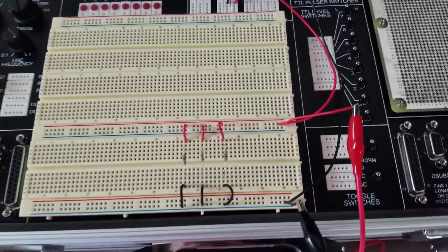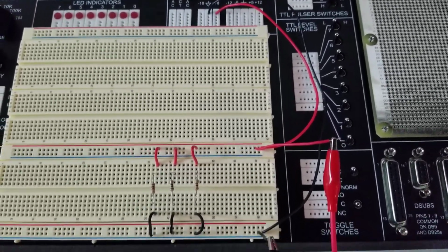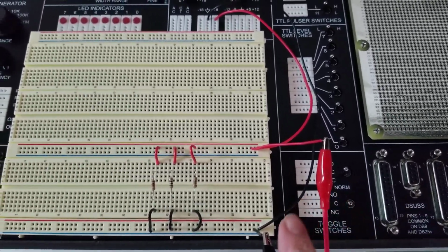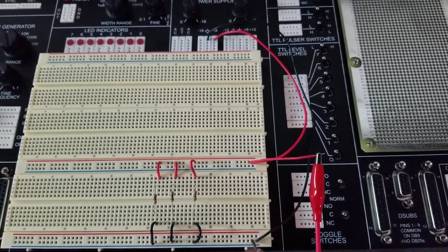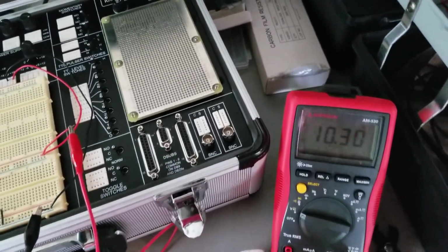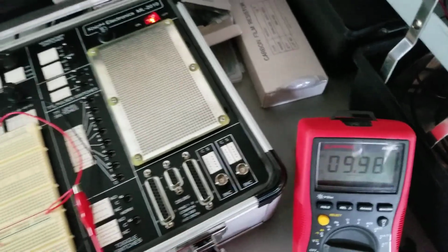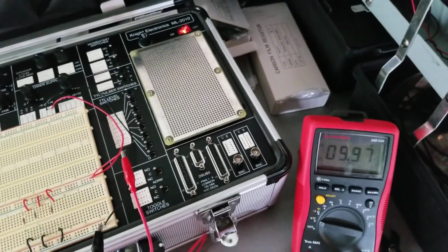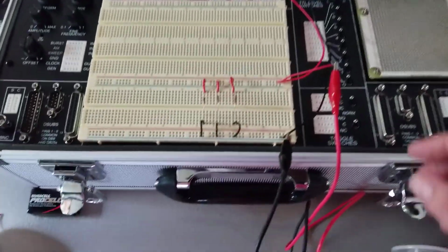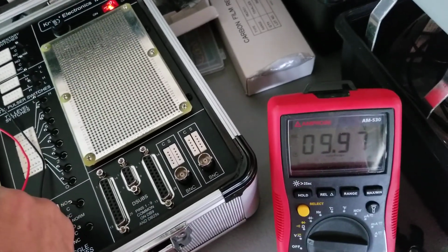Okay, I've now set up my 10 volts and applied it to my breadboard. Ground down here to the very bottom and power here. And I have my meter leads set up to measure the applied voltage, and just since I set it, it came up. Now if I come across each resistor, I should see the same 10 volts.